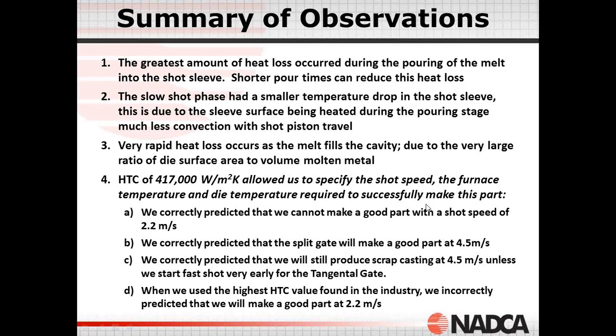So just to summarize what we've observed from this work, we found that there's a significant amount of heat loss that occurs during the pouring. So if we're having any kinds of cold flow defects, one thing to pay attention to is the method and duration of pour into the shot sleeve.